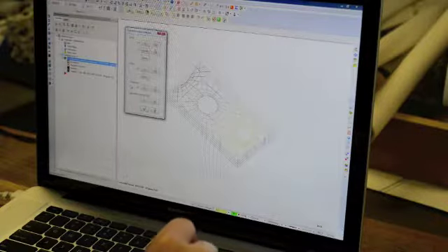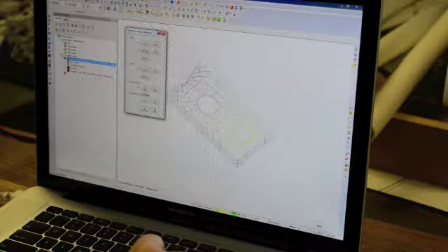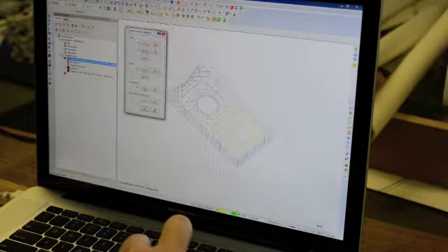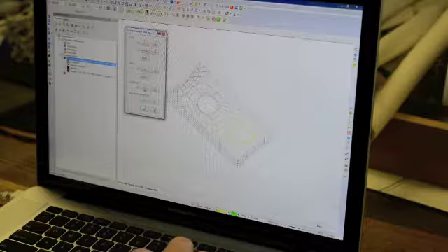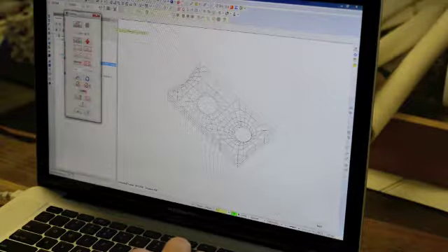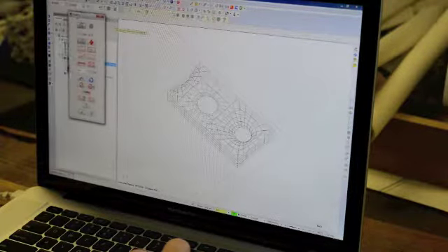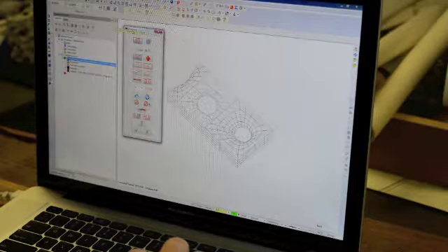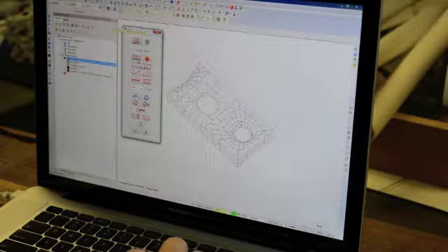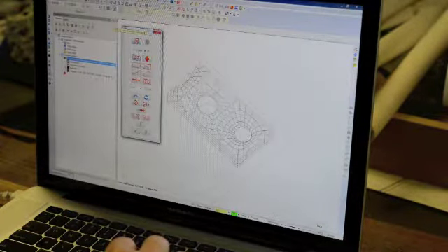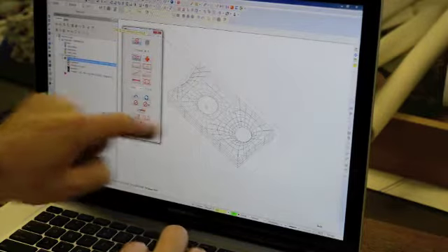And then containment, that's back where we had those curves that we created in Rhino. So let's select our containment. And the way this works is there's chaining. So right now, the way this is selected, it's a chain, so you'd be clicking on 1 curve, 2 curves, 3 curves, and it's just going to follow them in order.